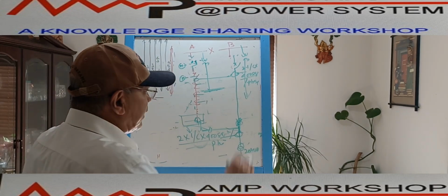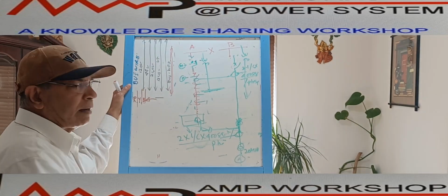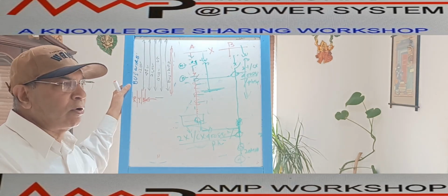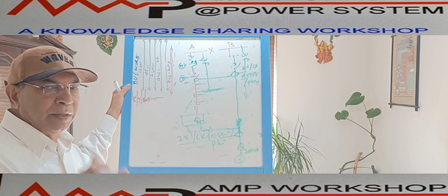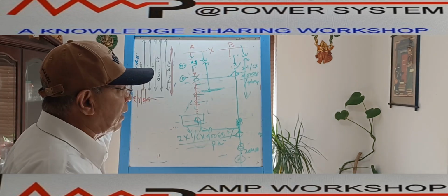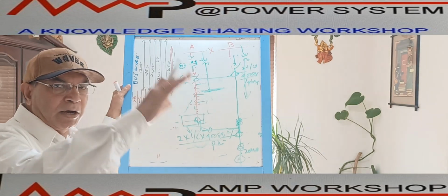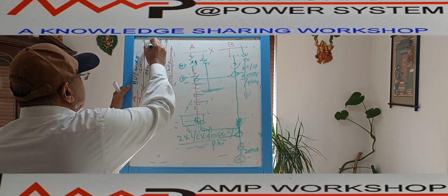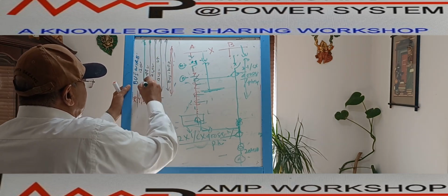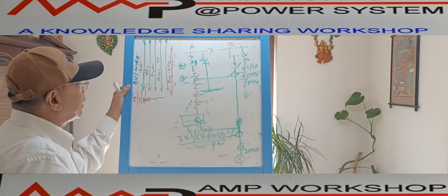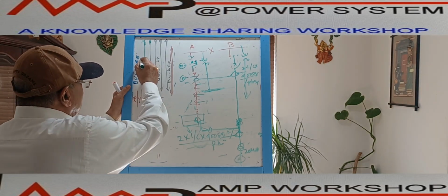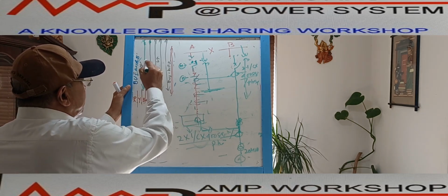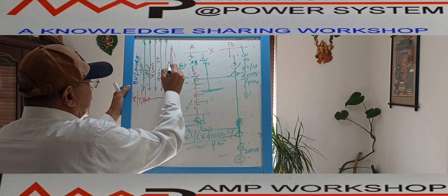So that bus bar, in addition to this bus PT supply, there is a control supply, 120 volt control, 48 volt control, 24 volt control, then your auxiliary supply. All this supply is going to the bus wiring. So that bus wiring we show inside the same drawing in this way. So this is a 120 volt bus bar which is running inside through one panel to the other, one end to the other end. From here we can tap 120 volt supply to the respective panel. Similarly, 48 volt, 240 volt, bus VT, bus bar differential.